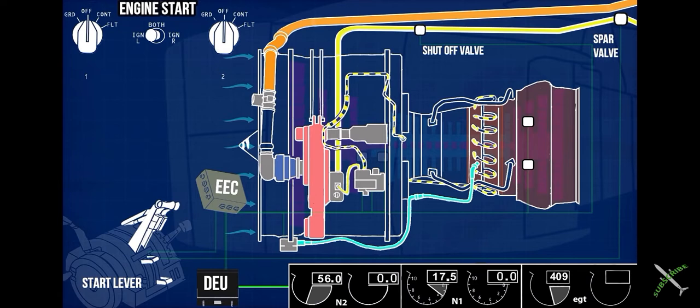The reduction in pressure reduces starter speed, which disengages the clutch, isolating the starter from the engine gearbox rotation. As the temperature inside the combustion chamber is enough for continuous fuel-air mixture ignition, EEC deactivates the ignition system. Now the engine has reached the idle stage.